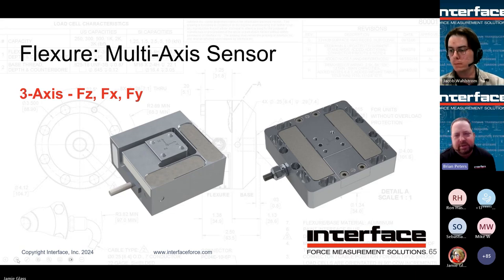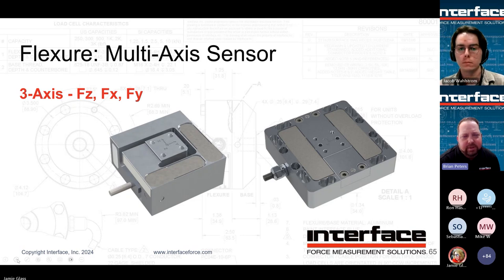So here's two different options to accomplish the same thing in terms of offering a sensor that will do FZ and XY shear. The one on the left, you can imagine was one big spiral there. So those are essentially 3 bending beam sensors bolted together. You can actually see the little gauge potting there that covers where the gauges are with the white areas. So you can imagine that they all kind of tie together.